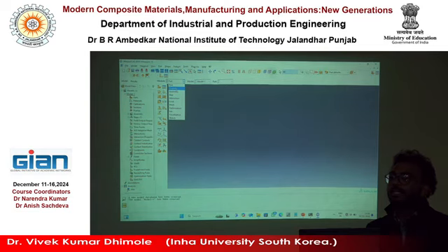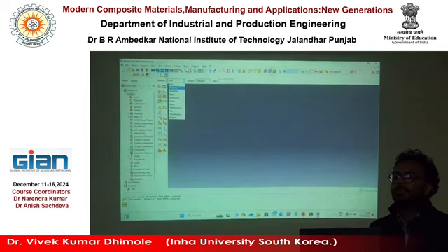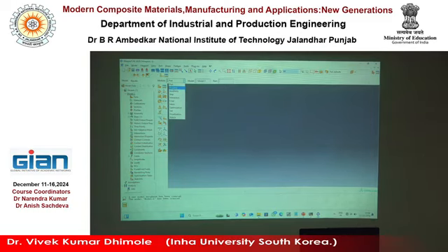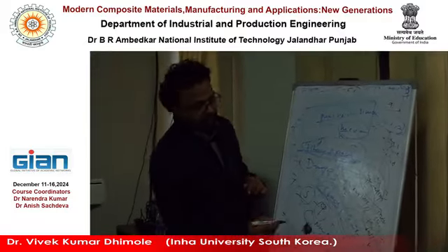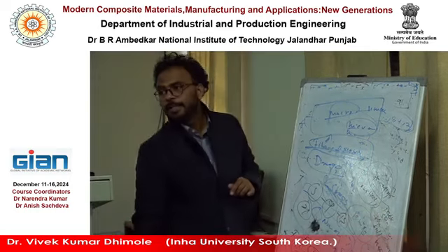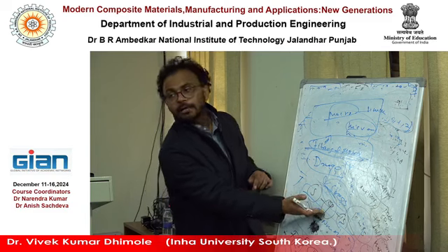So you can choose the material, either an isotropic material or a composite material. Here you decide the material, right? If you are choosing a composite one, you give the property either transversely isotropic, orthotropic, or anisotropic. There also you decide the system. 5 constants, transversely isotropic; 9 constants, orthotropic; 13 constants, general orthotropic; 21 constants, anisotropic, the complete one. So this is very difficult to calculate. That's why we sometimes assume 5 or 9.